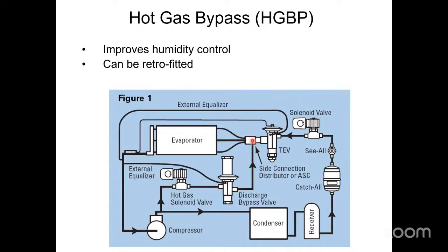And at first you're looking at that going, well, that seems stupid. Why do I want hot gas in the evaporator? Won't that make my evaporator warmer? Yes, it will. Why the hell would you want that? Well, if I have no way of turning my compressor off to get capacity control, I can falsely load the evaporator with the hot gas off my compressor to make it take longer to satisfy the thermostat and get a longer run cycle and hence better dehumidification and all of that.